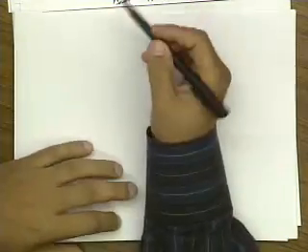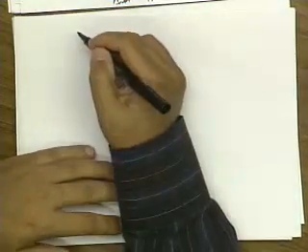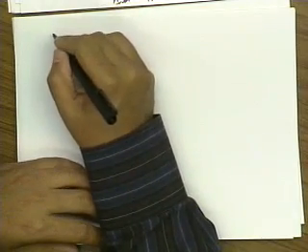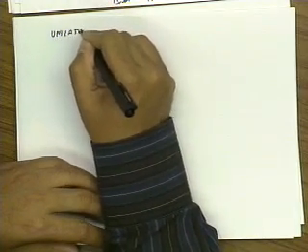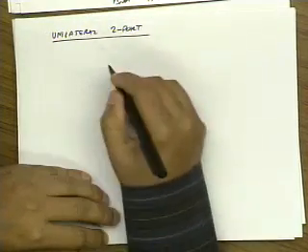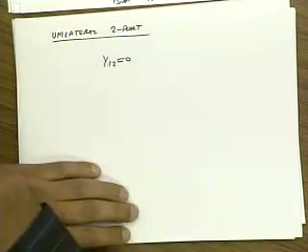All right. So now we have a nice recipe for doing a simultaneous biconjugate match. Before we go into the gory details, let's solve a simpler problem just to get some intuition for the solution. So let's look at a unilateral two-port. For a unilateral two-port, y12 is equal to 0.